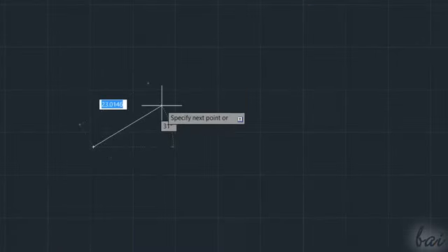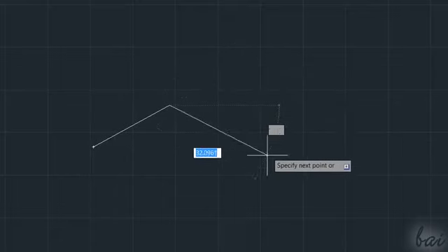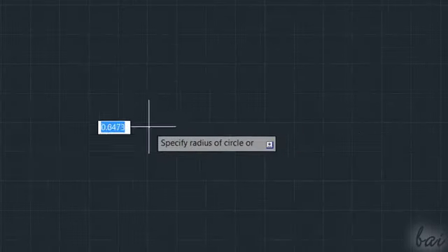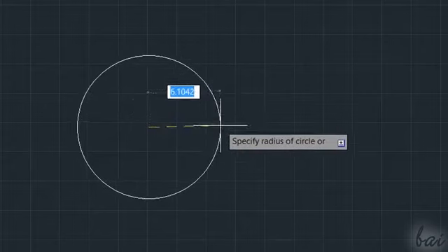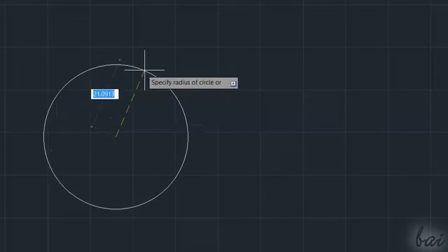While drawing, you can insert the exact length value on the current side by typing directly from your keyboard and applying with the Enter key. Remember that the object is placed when you fix enough points for it. To undo your drawing in progress, just use the Escape key.